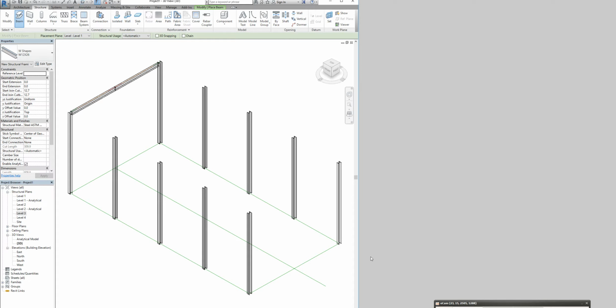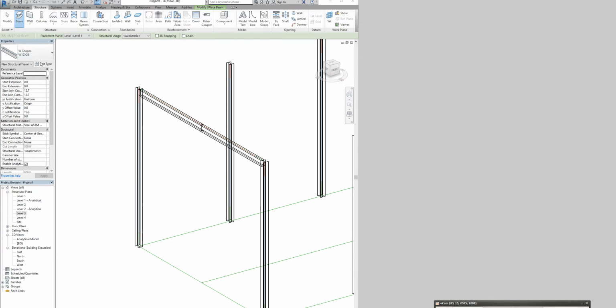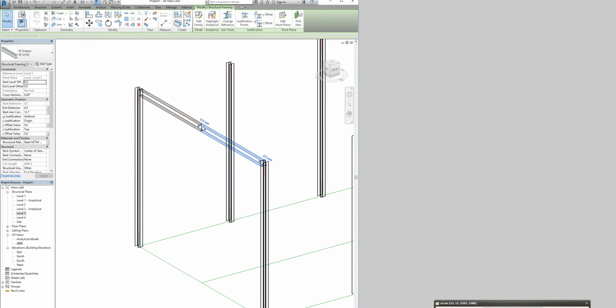and correct pitch using a sketch arrows. So we select this beam, and we're gonna put 500 shown here, and then 500 on this other. That's good. We have same scenario as the slides, so this one is longer, this one shorter. So we are going to correct this pitch.